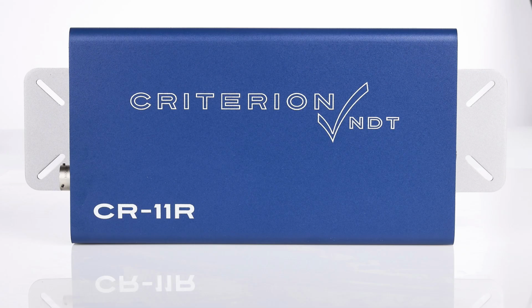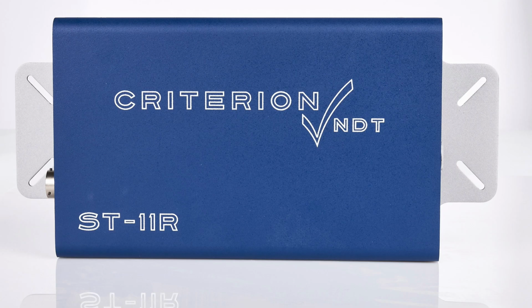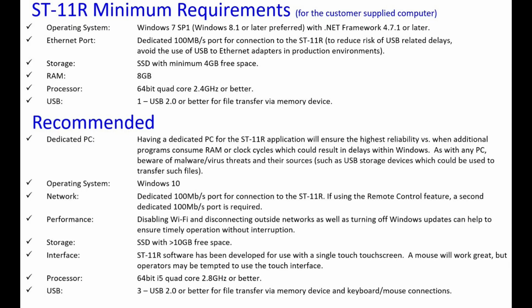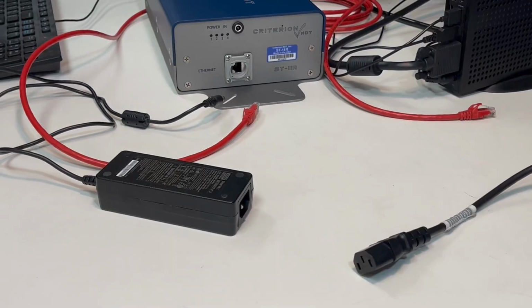This video shows the initial setup of a Criterion NDT CR-11R or ST-11R eddy current test instrument. Let's jump into it. First, ensure that your PC meets the minimum requirements listed in the CR-11 or ST-11R manuals.